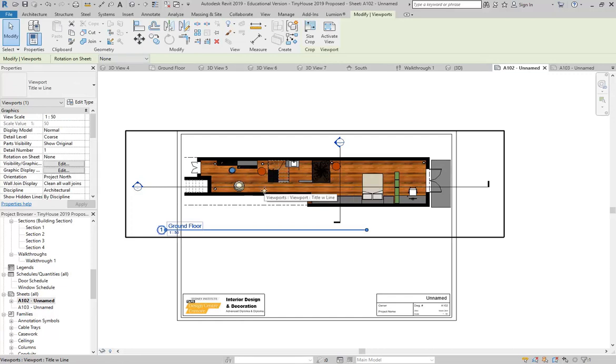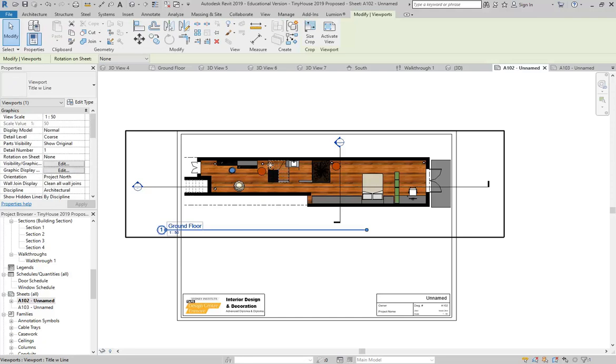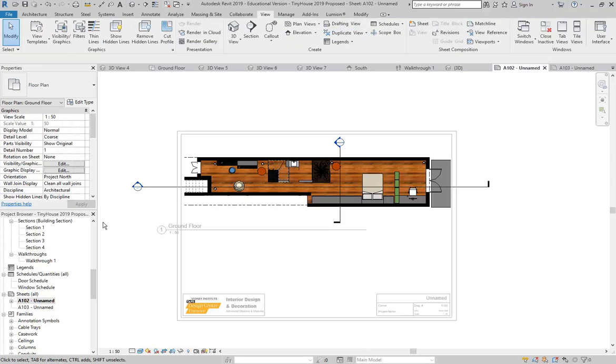Well, you'd have another plan that shows the whole thing. And that's actually a good thing I can show you. So here you can see, it's okay, but the section lines now are obviously going off the page. If I've got that view selected, I can activate the view, and then it's just like AutoCAD, where you can switch between model space and paper space. And so now I can do all the things I was doing before.